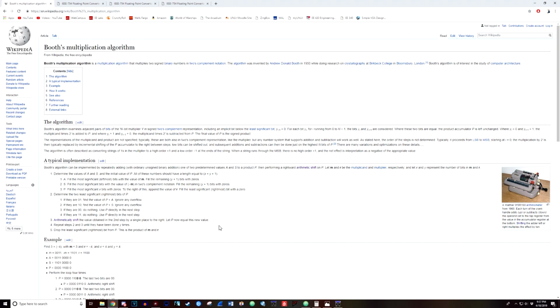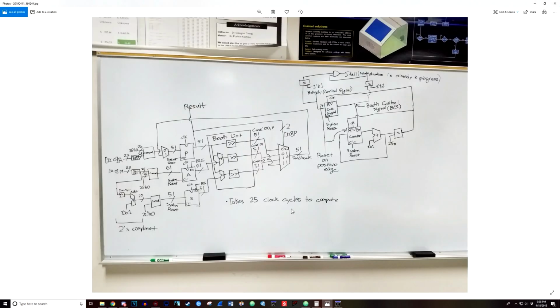So the most difficult part about this part of the project is to multiply two large numbers efficiently, specifically the mantissas, which are 23 bits. With the implicit one, it is a 24-bit multiplication. So that is going to be a big challenge. I took the opportunity to study the Booth's multiplication algorithm, which will efficiently multiply the 24-bit numbers every 26 cycles. So it is very efficient versus the brute force tactic, which can vary from 15 cycles to maybe even 1,000 cycles. So the algorithm was translated into hardware on the whiteboard.